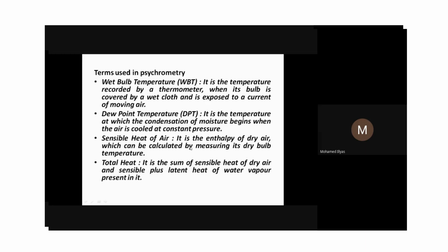But we need to understand the difference between sensible and latent heat. The sum of sensible heat and latent heat is the total heat here. The temperature here is constant, and in the same way it happens here. We have a temperature rise here. Since there is a temperature difference, the heat will be given here. So it will cool.